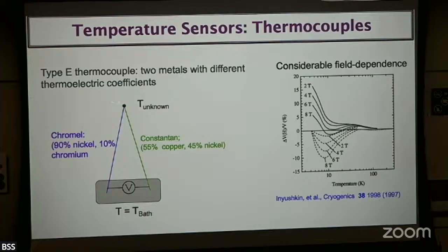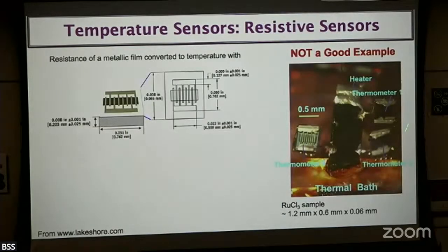And especially when you measure the temperature gradient, you're using two thermocouples, and the two thermocouples must have the same temperature dependence and so on. But this is a very big temperature dependence. Look at this, percentage-wise, it's really not so great. Even at higher temperature, like let's say 30 Kelvin, 5%. I mean, 5% sounds small, but when you translate that into such a small temperature gradient, it doesn't feel safe at all. Next thing we're using is the Cernox sensor.